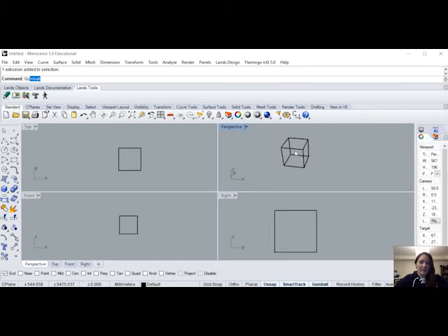You can also type in Gumball, and then you can toggle it on or off. Right up here, you can either click or just type O, because it's underlined. Whatever letter is underlined is the command for it. So O is the command to toggle it on.